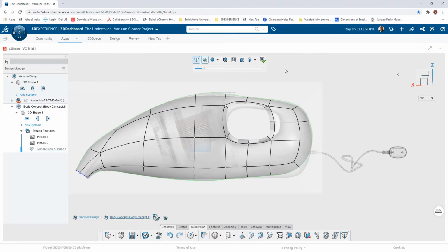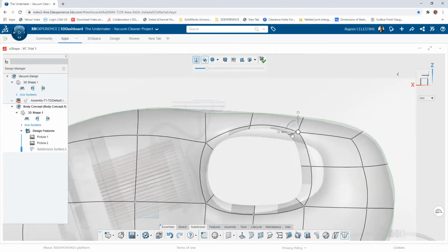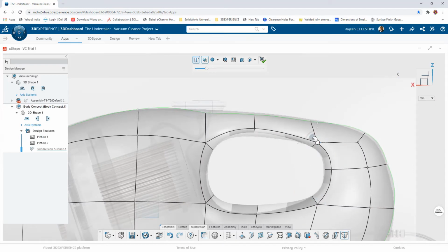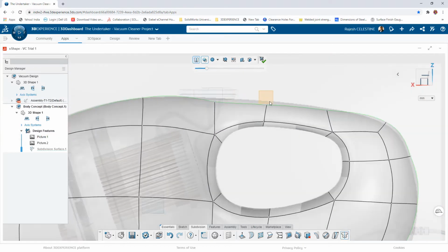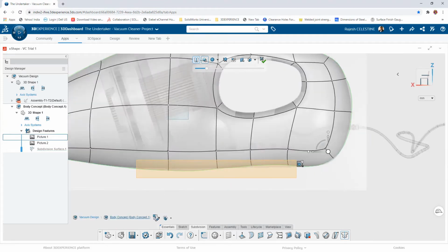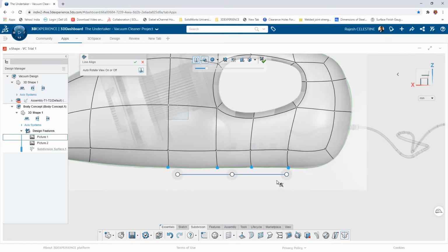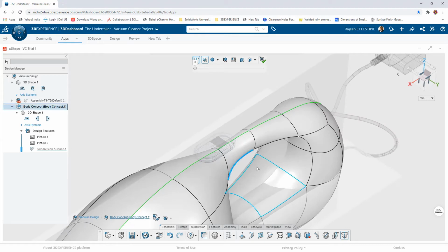Having completed this, it now makes it easier for me to shape my vertices to align the shape of the handle and complete my design. Here it is needed to align the bottom vertices as I require to have it aligned to a line. Selecting the bottom vertices and choosing the line align option helps me achieve this. A portion of my handle needs to be stretched, where I could select the edge and move it with the triad.